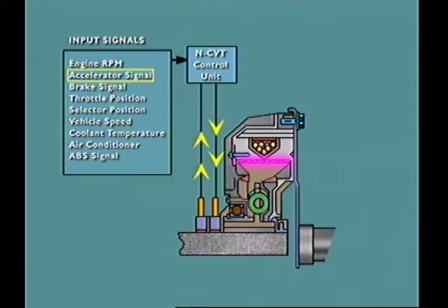The powder locks the engine rigidly to the transmission input shaft. With the engine off, or the selector in park or neutral, reverse direct current sent to the coil demagnetizes the clutch powder and releases the clutch completely.